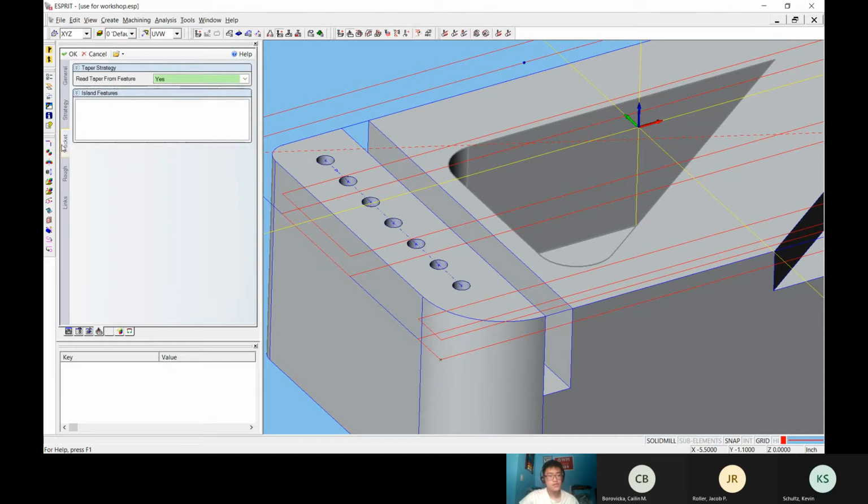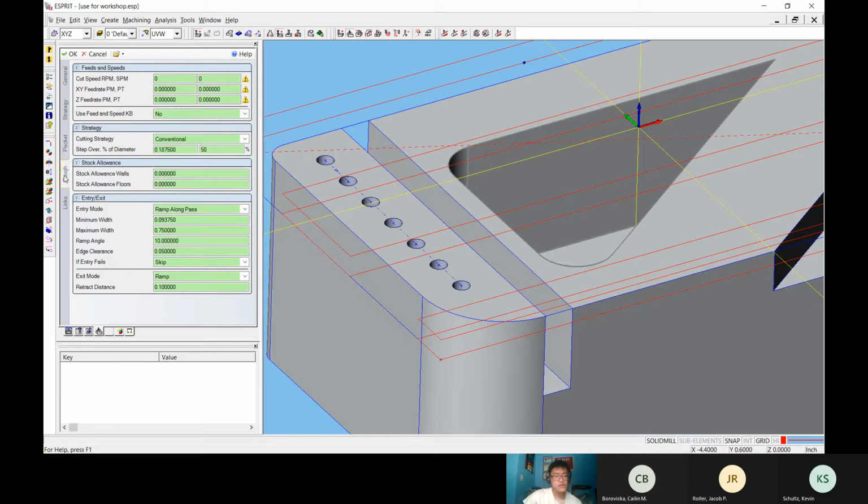Let's see, what's in the pocket? Okay, so the pocket tab, which we'll use in something else today, but we're gonna move on since we don't need it. We're just gonna go to the roughing tab, and this is where it is gonna ask us to put our speeds and feeds. So if you remember, when you're using end mills, you're gonna want to set your RPM to whatever the max RPM of the machine is.